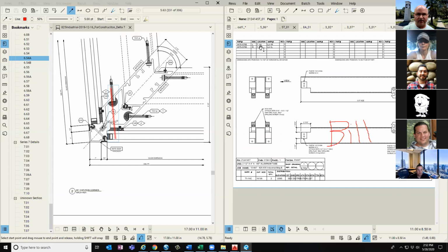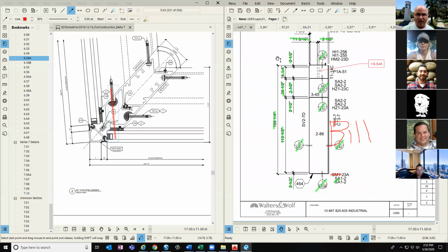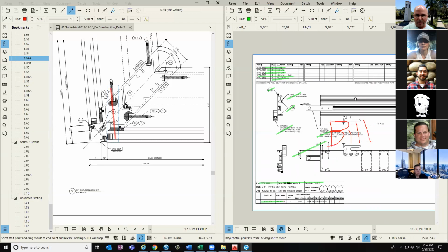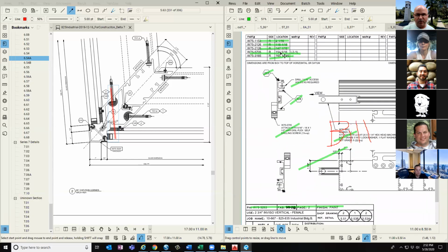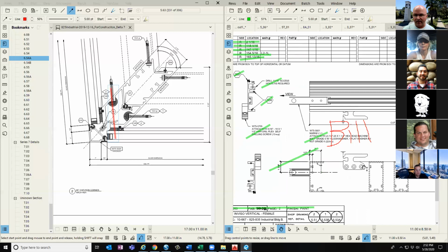Then I've got the height here. So in this case, I've got a 7¼ inch dimension. Well, if I look at my vertical here, I can take the difference between the top of the hook lug, the 154 and 5/16, to where the next horizontal is, which is where that pony tube's going to go. So picture the pony tube fits inside of this area.